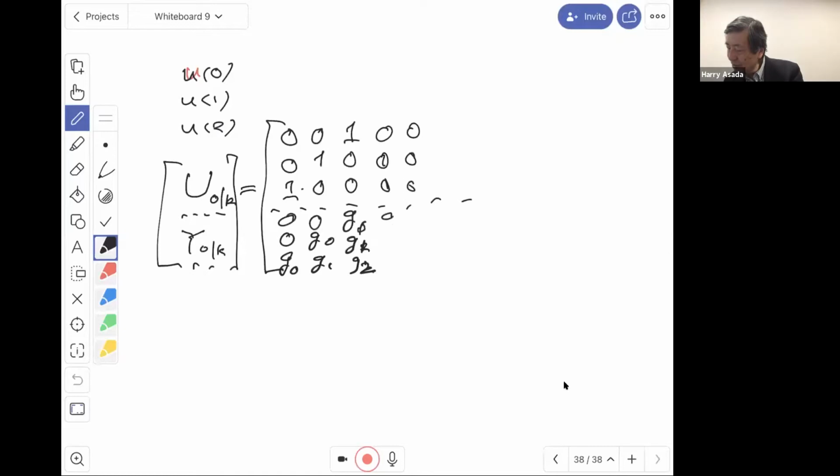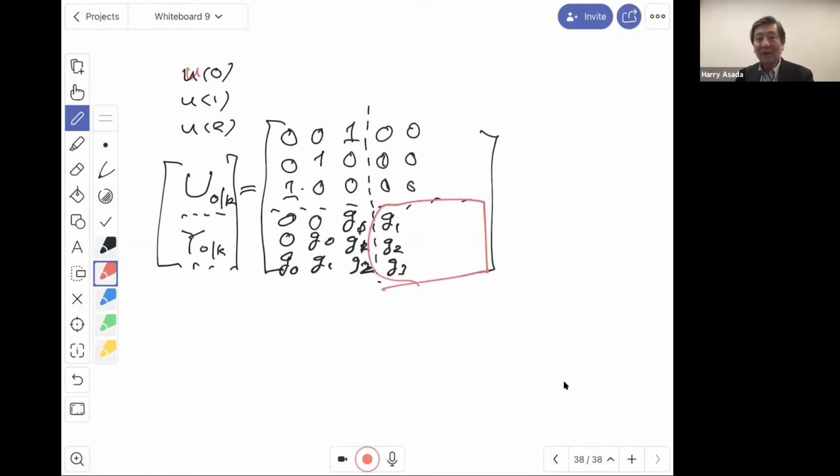And then here G1, G2, G3, and such, right? So you form this kind of data matrix, and in the whole Kalman method, we look at this block, right? And this block has a very specific Hankel matrix structure, and all the impulse responses, the G's, are involved here.